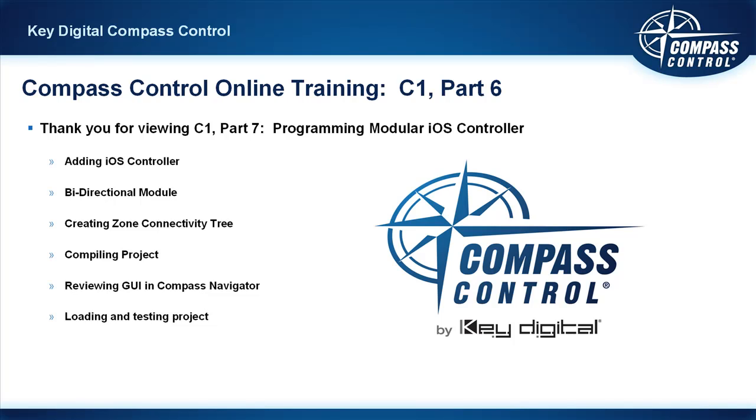So yeah, just going back to step number 1 in that programming tab, adding the controller that is the iOS device, adding the device ID in there. But then also remember, in our adding controllers, we did import the XML from the Lutron device, which created a separate bidirectional driver. Because the Zigbee remote control driver has all of the one-way control in it. Because after all, the KD-ZRC300 has no LED display, for example, so it's one-directional control. It's very simplistic.